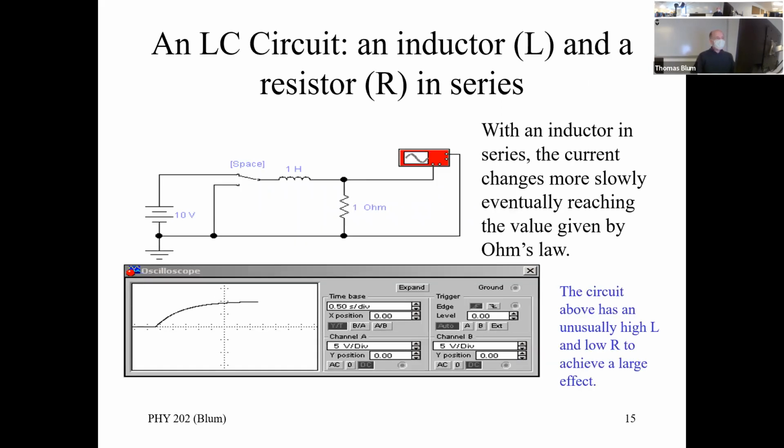So here with the inductor, this little coily thing, this 1 Henry inductor, I brought in and it slowed this down. You know and love this shape, or you know and hate this shape. This is the same shape as for the RC circuits. So our 63% is back, our 37% if we're going down is back. So if you didn't learn it the last time, learn it this time. If you learned it the previous time, good, it's the same.